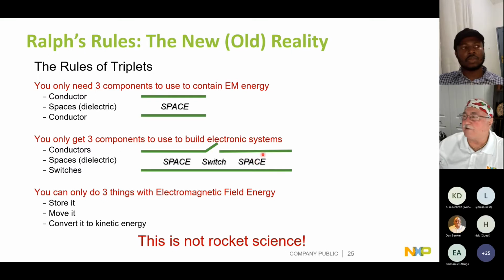And that's why we were lulled into submission by slow transistors, because the displacement current was spread out across time and the physical space in this conductor. And it wasn't energetic enough to cause problems. So this is the idea. And so from that perspective, yes, there is some current flowing in a loop, but it doesn't carry the energy.